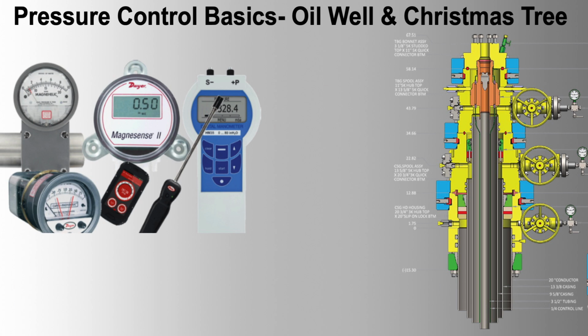Example 4. Surface pressure sensor for hydraulic fracturing. Design. Piezoelectric sensors are suitable for capturing dynamic pressure changes during hydraulic fracturing. Monel K500 is chosen for its robustness in sour service environments. Selection. The sensor's accuracy of 0.25% and high-frequency response are essential for monitoring pressure spikes during fracturing. The quick connect fittings and explosion-proof housing facilitate easy and safe installation on the fracturing manifold.